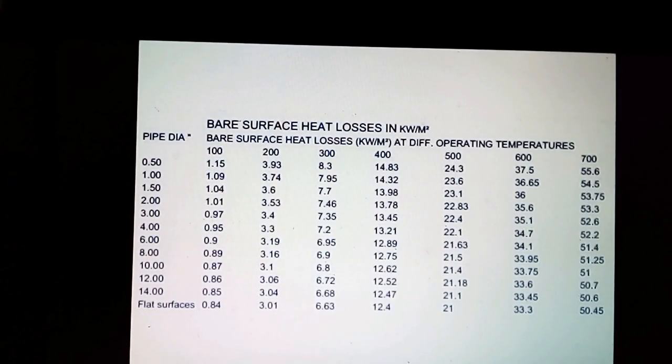Small steam pipes should have the same insulation thickness as large ones, as the heat loss per square meter on a small pipe is higher than on a large pipe. The insulation manufacturers publish insulation efficiency data for different thicknesses of the different grades of insulation. Such tables generally provide the efficiency data against two variables: pipe size and temperature difference. The amount of insulation to be applied is an economic problem like many other power plant design problems. The cost of insulation must be weighed against the saving of heat energy obtained due to insulation.